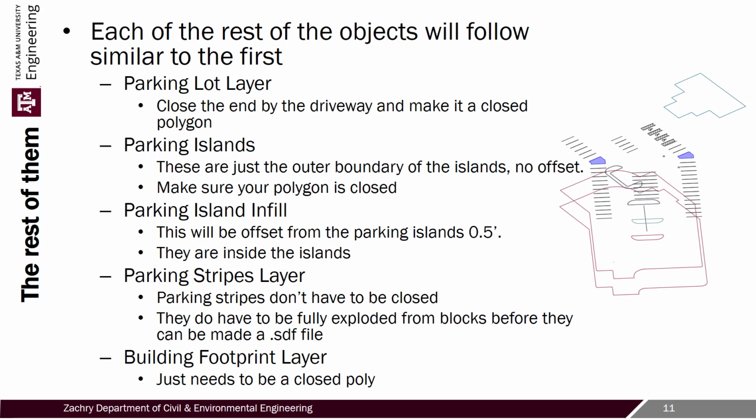So all I have to do is make sure that I add all of those in there. Same step, going to make an SDF, but there's not really any big rule. The only rule that you need to follow is with the handicap spaces, because those come in as blocks and you want to make sure that they're fully exploded. If you don't, then they're actually not going to come up because these programs don't like blocks.